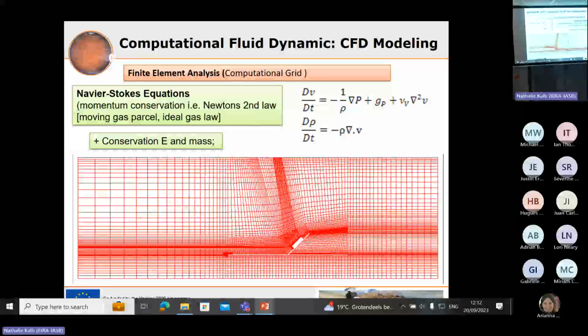We tried a long time ago. So this is a model of an actual thing that we built. This thing here, which actually ended up being sent to Mars. And this is the wind tunnel. The wind comes this way. So what you do in a computational CFD model is you split it up into a matrix of whatever pixels you could call them. And the important thing in that process is that in some areas, nothing much happens. So you need really poor resolution. And some areas like this little guy down here, you need an insanely large number of actual elements.